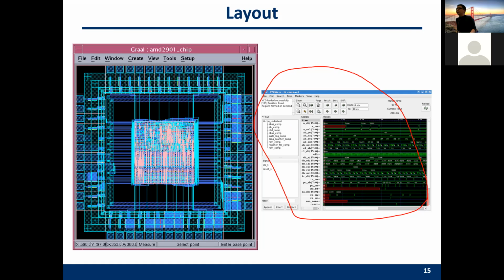So when you consider the real gates, you need to do some post layout simulation, where you take all the parameters of your real gates into consideration in the simulation. But again, in homework 1, we do some AND OR gates, and these are pure logic simulation. We have no real gate at all.